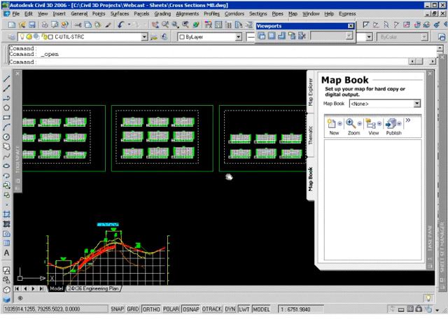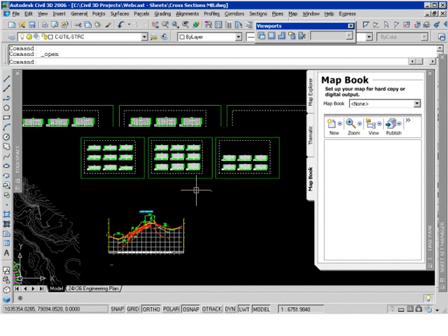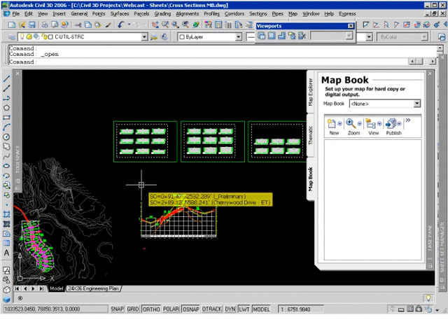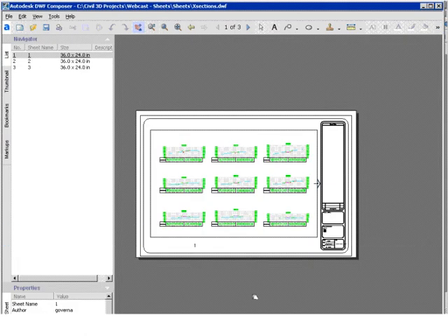All right, well, I don't want to waste people's time here with some sort of mispick that I'm making. But the idea here is what the map book does for us is instead of having to go manually create those sheets in each drawing, an XREF in the information, what it'll do is physically create the layouts right here in our drawing. So it's kind of two different methods using Sheet Set Manager. Do I want to use an XREF technology and have a separate drawing for each layout? Or do I want to use the map book technology where I can come into this drawing and have layouts created for me, each of those layouts being right there in that drawing and pulling from information in that model space? What I do have is the DWF version of that.